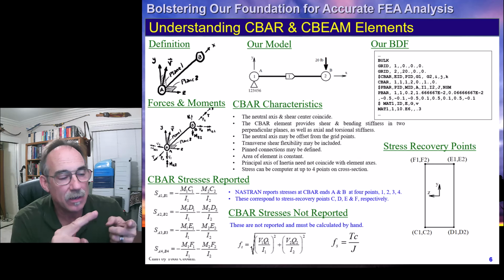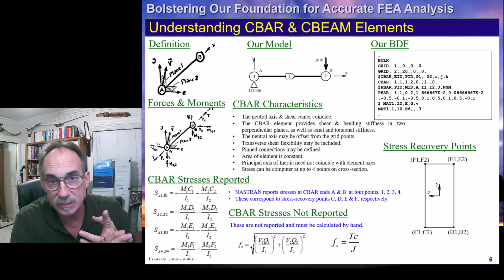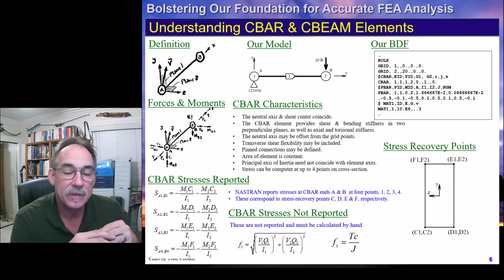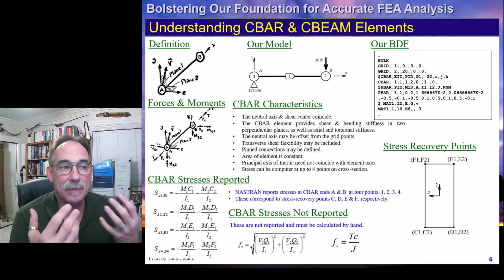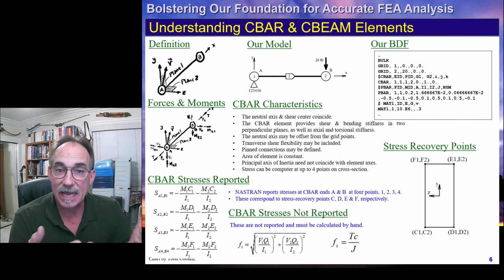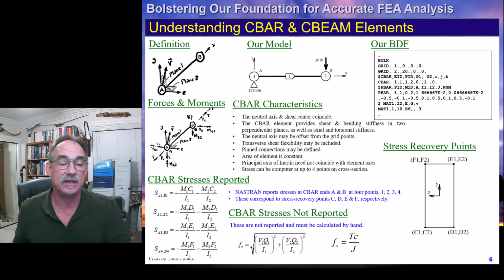So it's important to understand what NASTRAN bars and beams can do, what the stresses are that are reported, and which stresses are not reported, and be ready to generate those as needed so that we make sure we have all the right margins of safety written for the structure.